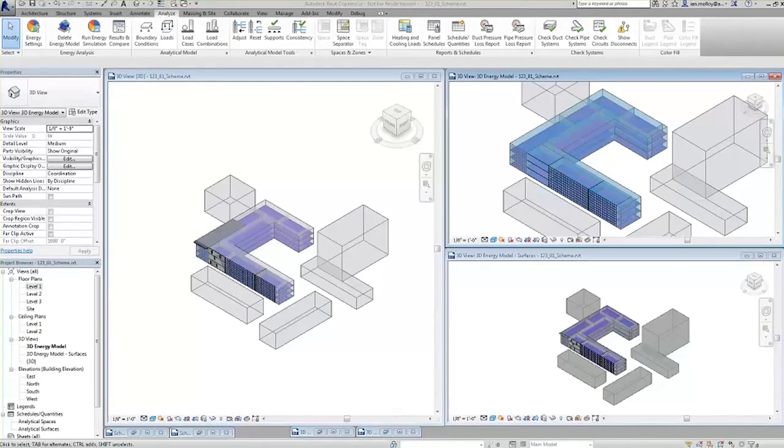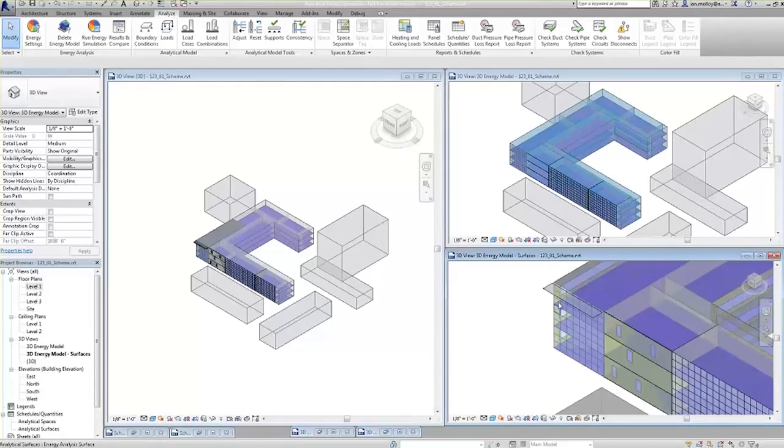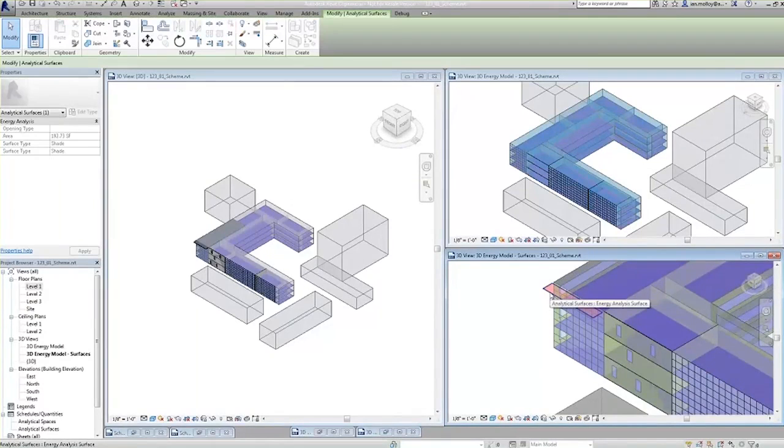typically in Revit models. So the other thing I just wanted to point out as well is that just because I added this roof with an overhang, you'll see if I zoom in here, that's now actually been interpreted as a shade because that part of the roof is not actually bounding any space. It will, however, be casting shading on that glazing. So if I wanted to understand the behavior of that, I could do that.